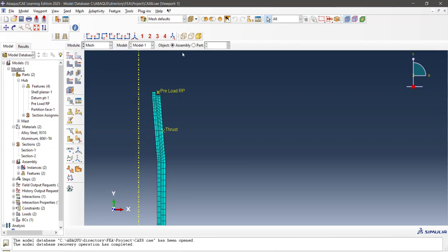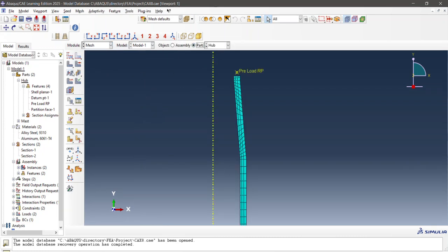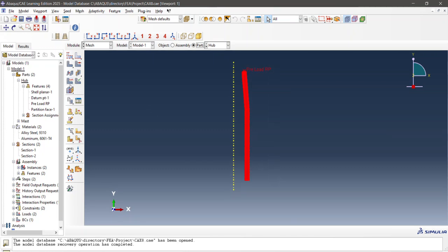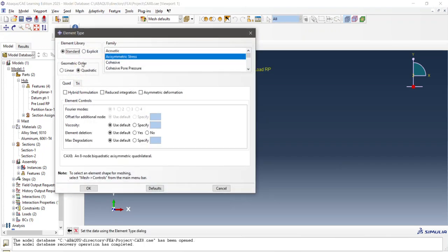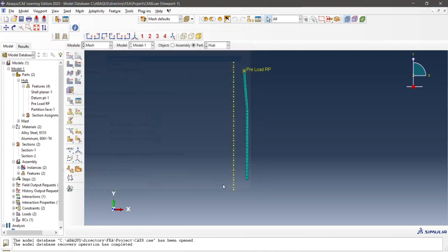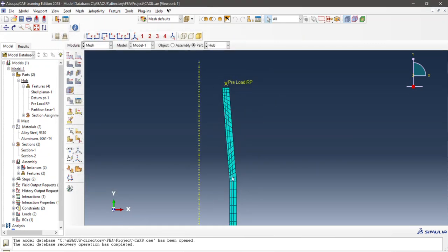So my mesh, since I'm using an axisymmetric model, I'm kind of limited on what I can do for the most part. So I'm choosing to do a quadratic because it can give you a more thorough calculation of what the behavior is. I mean, you're going to have 8 points to go off of versus 4 if I did it linear. And then it's a quadratic, right? So I'm just going to get higher resolution. And then it's going to enable me to use fewer nodes, right? So that's great. And that's why I chose to go that route.